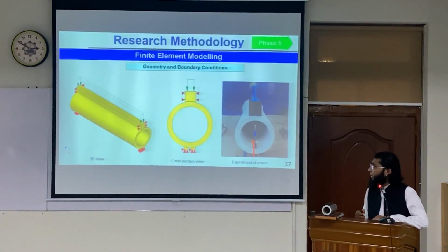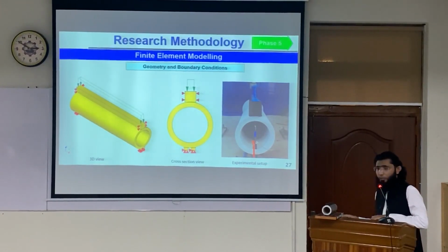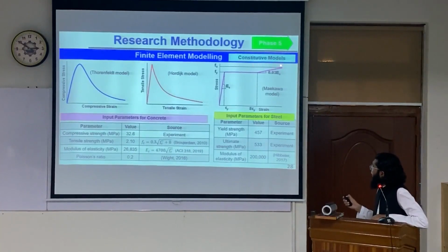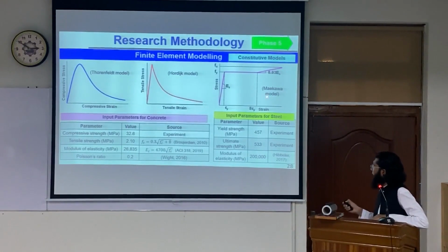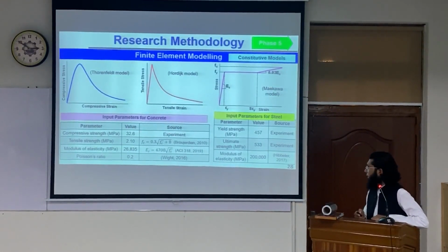And lastly, the finite element modeling. The geometry and boundary conditions are shown here. The bottom was restrained and the loading was applied to the top to replicate the experimental setup. These are the constitutive models that were used: Thorenfeldt for compression, Hordijk for tension, and Menegotto-Pinto for the steel bars. These are the different parameters used to define these models.